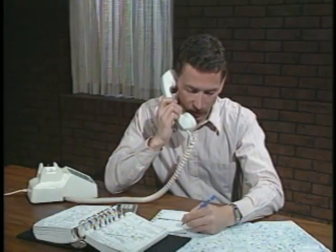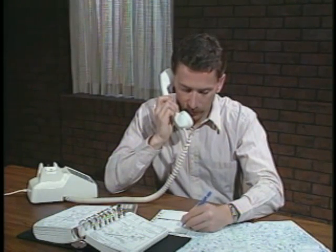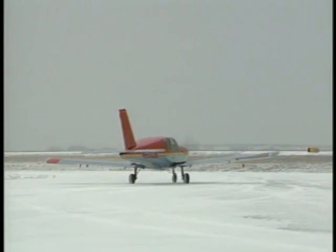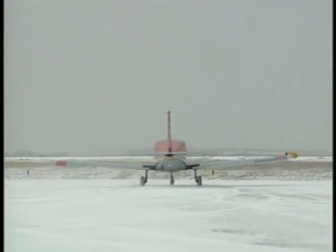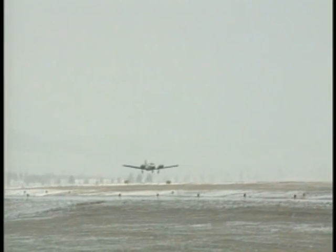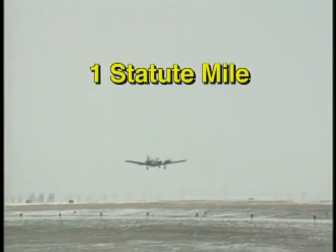By regulation, before any IFR flight, you must check the en route weather and the weather at your destination and departure airports. For commercial flights operating under Part 121, 125, or 135 of the Federal Aviation Regulations, certain visibility requirements must be met before a takeoff is allowed. While these minimums are not required for flights conducted under Part 91, they are good guidelines for you to follow. For aircraft with one or two engines, the standard visibility minimums for takeoff are 1 statute mile.